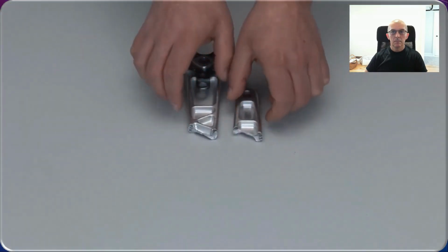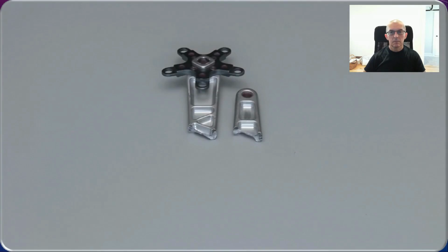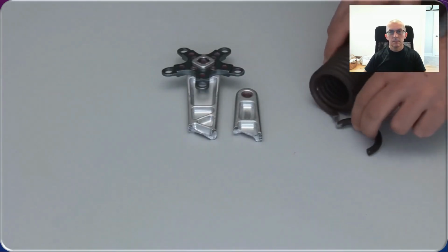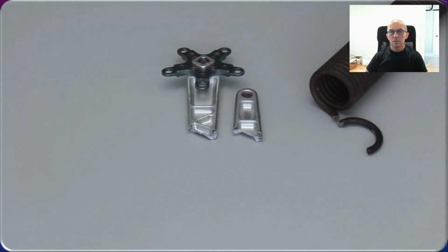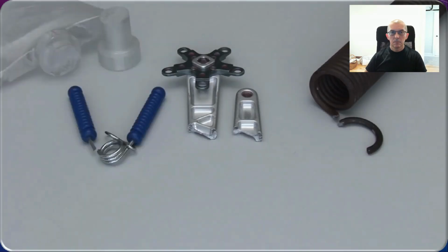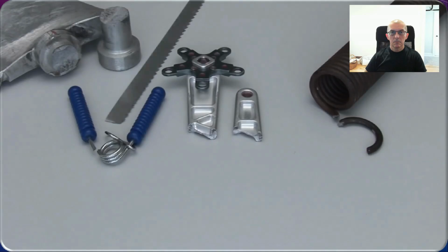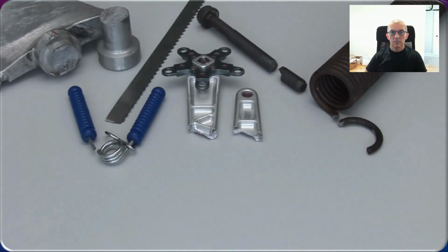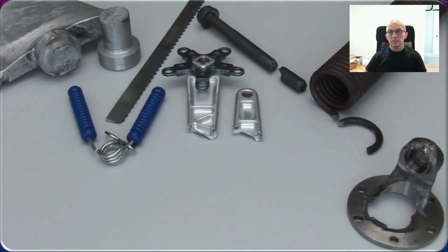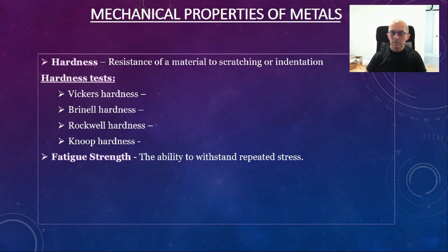This bicycle crank arm had only been able to endure the cyclic loading for a certain time before it broke. The fate of the garage door spring was the same. It had borne the opening and closing of the garage door about 60,000 times before it finally fractured. The broken exercise equipment, a torn blade of a fan, a bandsaw blade full of cracks, the broken screw, a defective universal joint, and many other examples show how important this phenomenon is. Okay, so that's fatigue strength.